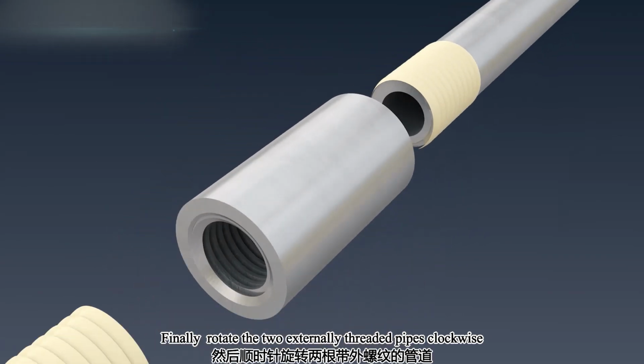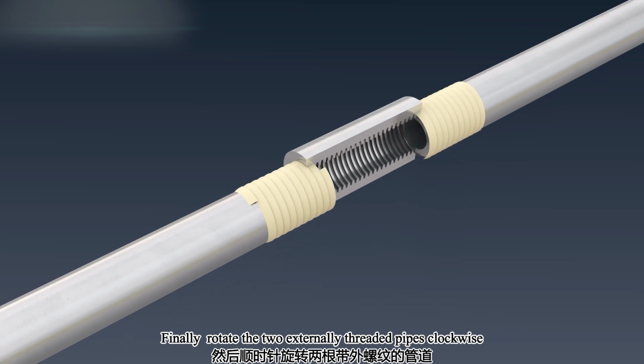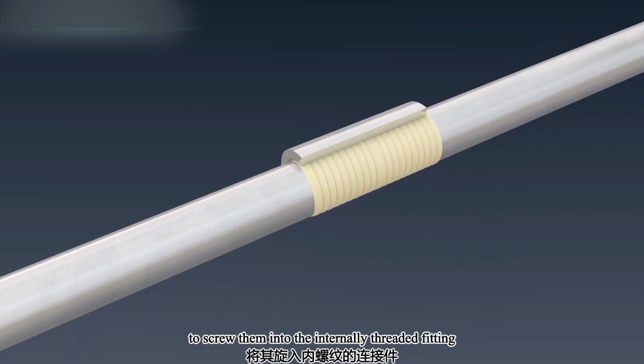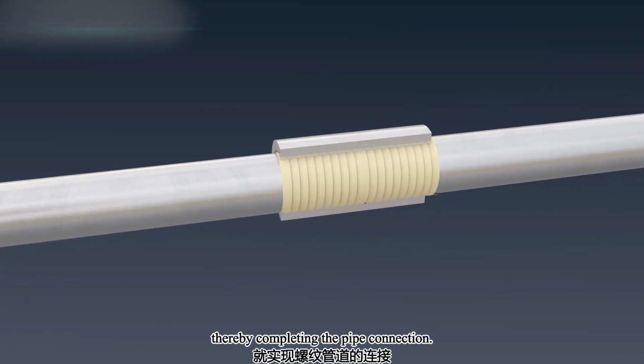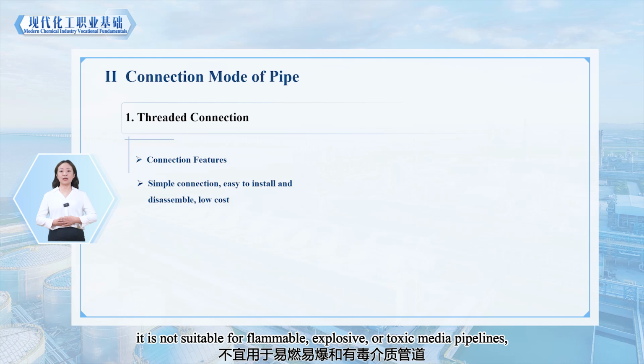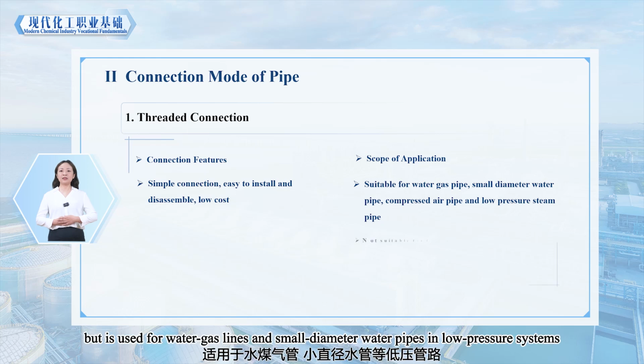Finally, rotate the two externally threaded pipes clockwise to screw them into the internally threaded fitting, thereby completing the pipe connection. This connection is simple, easy to assemble, disassemble, and low cost. It is not suitable for flammable, explosive, or toxic media pipelines, but is used for water gas lines and small diameter water pipes in low pressure systems.